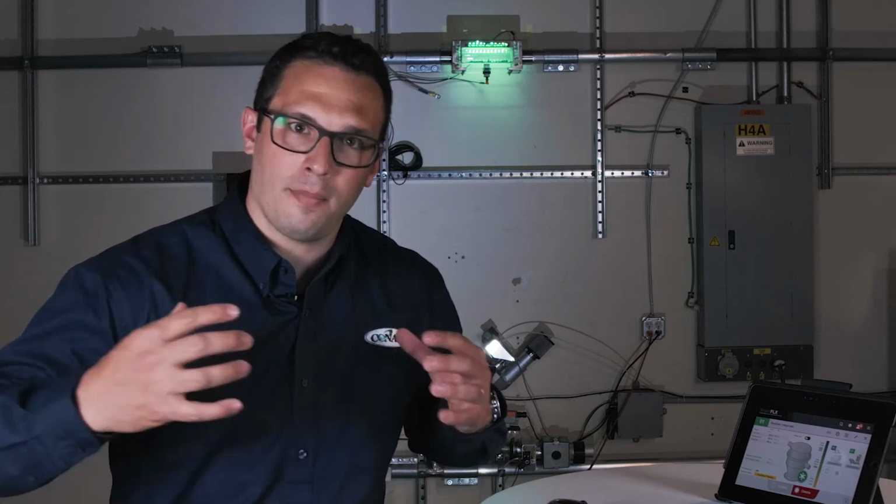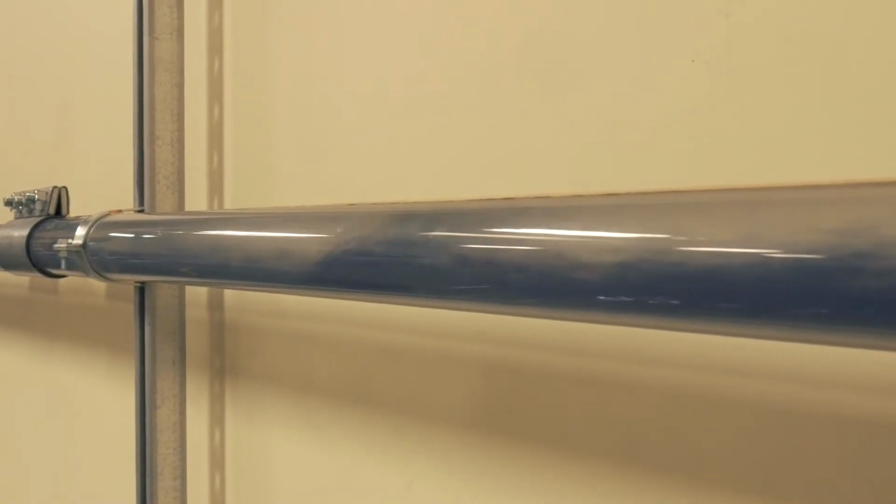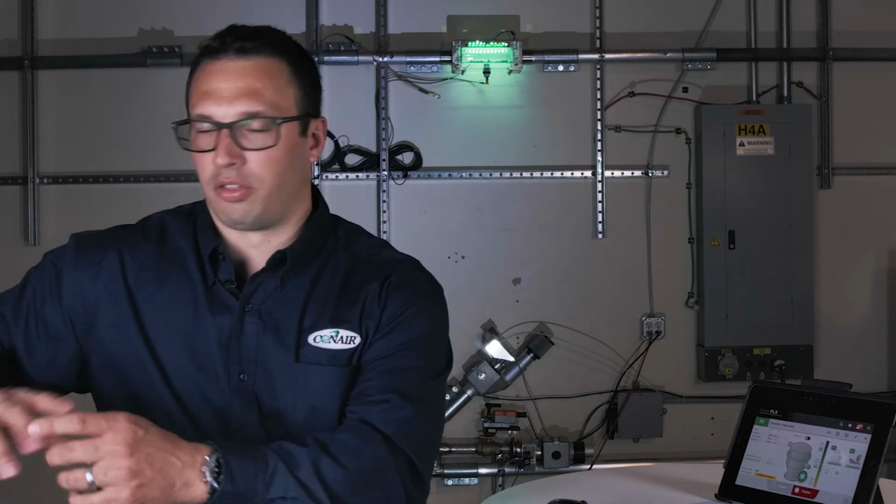What we're doing with wave conveying is we're getting the material picked up by achieving that 3,500 to 4,000 feet per minute, but it's not continuous. Our patented technology allows us to pick material up in cycles and keep it moving very slow. So low pickup velocity with respect to that first acceleration zone of your material handling line, and keep that material moving extremely slow throughout the full conveying to your receiver.